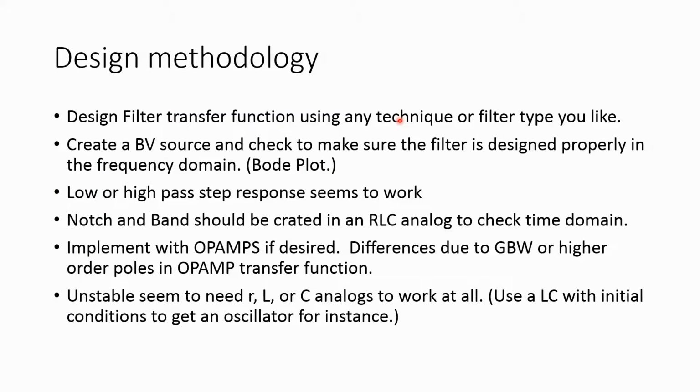So what's a designer to do? Well, I would design a filter transfer function. You can use Python or come up with your own coefficients, and you can choose Butterworth or any kind of filter that you happen to be doing. Then to verify it in LTspice, create a behavioral source and make sure that the filter is properly designed by looking at the Bode plot.